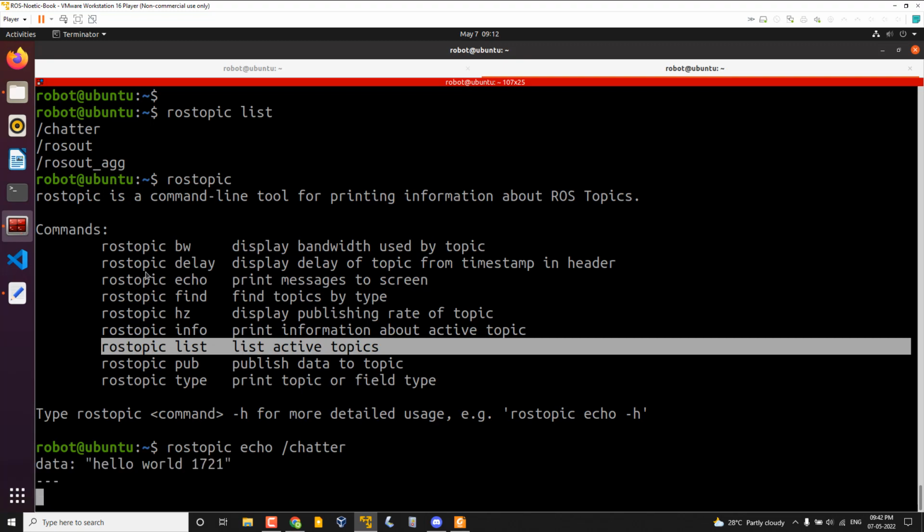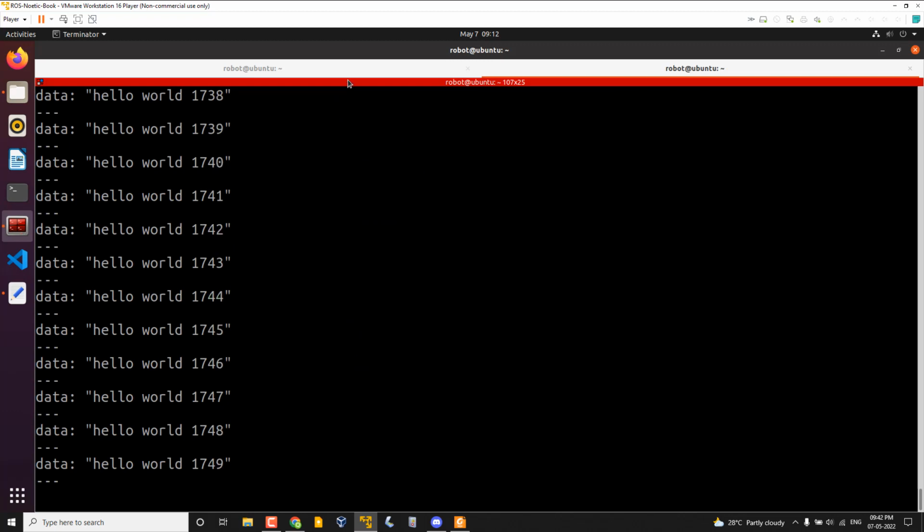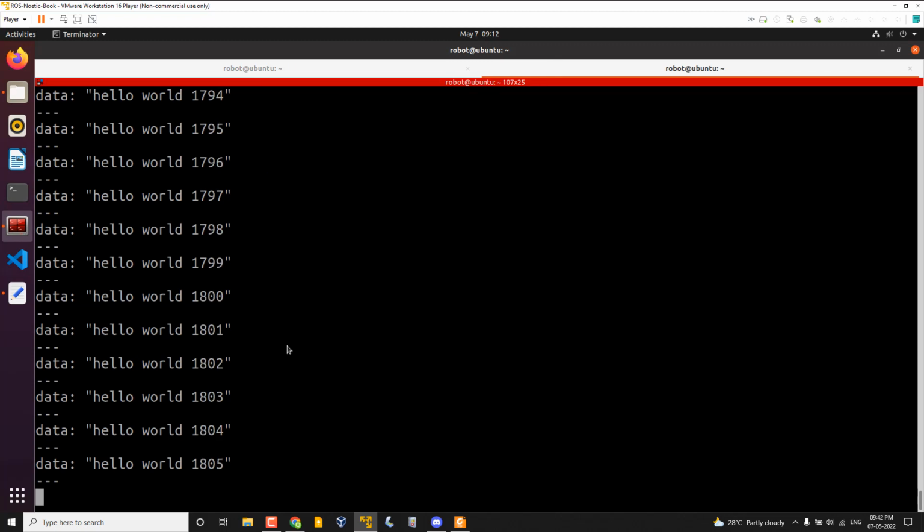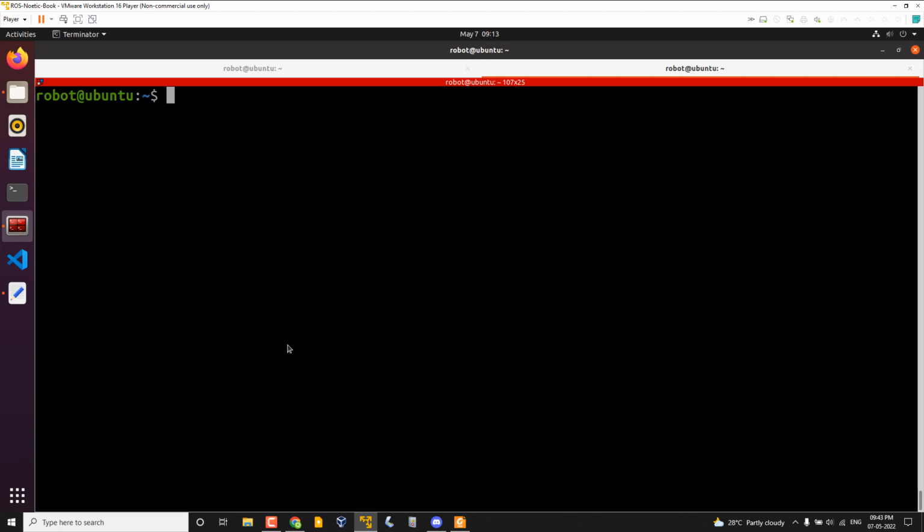When I press enter, you can see the data published by the talker is subscribed by the rostopic command line. In order to view the data, you have to subscribe. That is what rostopic echo does. This is the syntax.